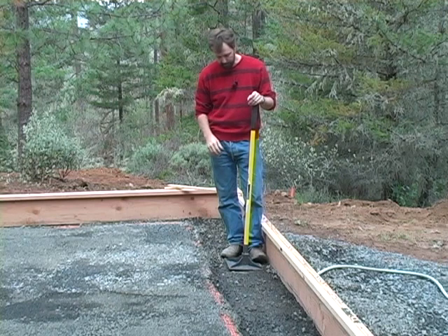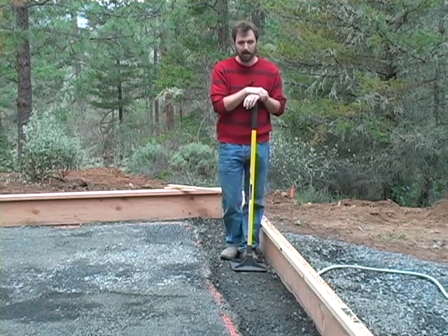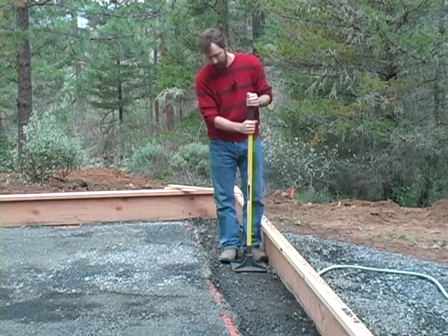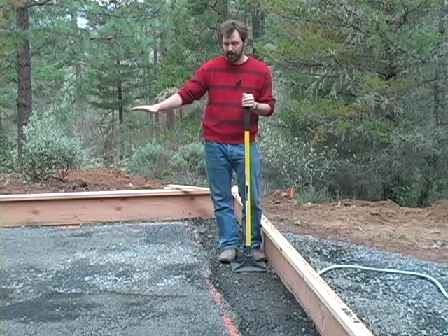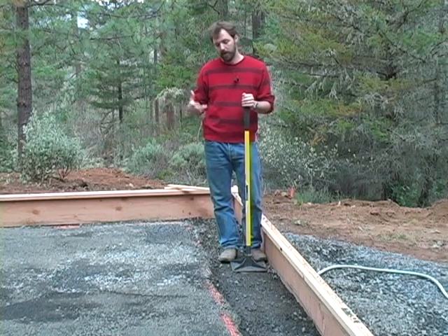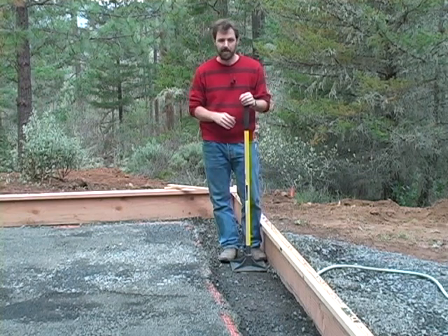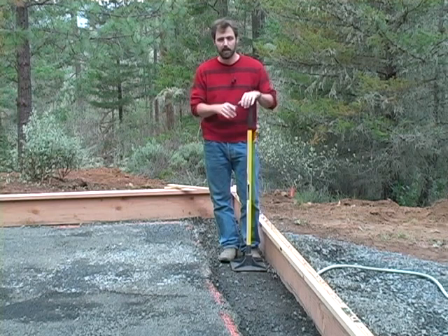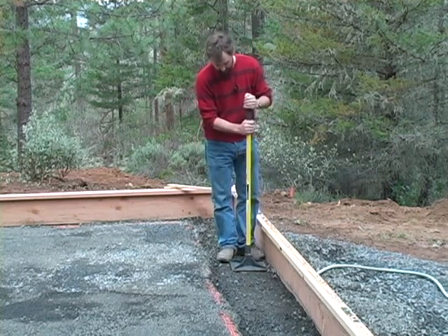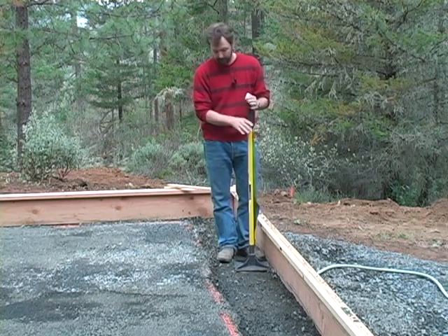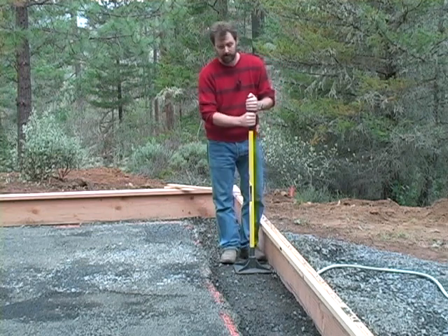After we've cut out our footing, we want to go back with a hand tamper and compact any loose gravel that's come up in the bottom of the footing. Now, whether you're using the hand tamper or the plate compactor or really any kind of compactor, it's important to have the material that you're working just slightly damp. You don't want it to be wet, but you don't want it to be dry. With a little bit of moisture in there, it really helps the compaction. Otherwise, when it's dry, it just wants to separate, and when it's wet, it just creates all kinds of a squishy mess. So again, you want to just have things just lightly dampened. Now I'll walk down the whole footing here with the tamper, flattening it out as much as I can and just putting that last oomph on it before we go and get ready to set up for the pour.